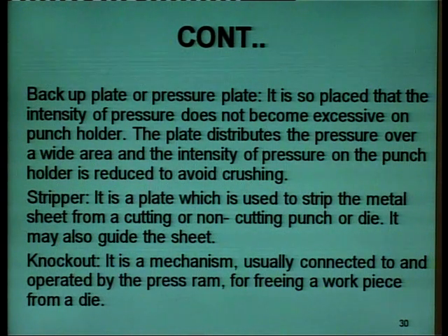Next comes the stripper. Now, it is a plate which is used to strip the metal from a cutting punch or die, means to remove the metal from a punch or die. It also acts as a guide to the sheet.